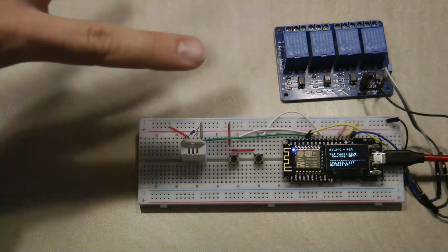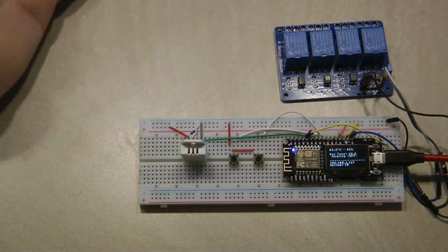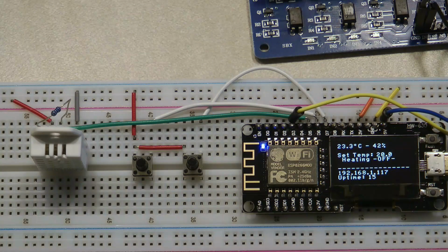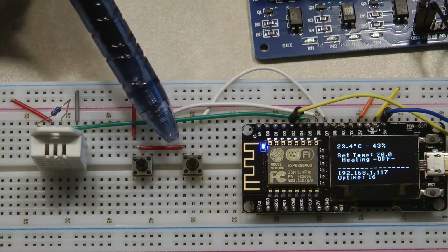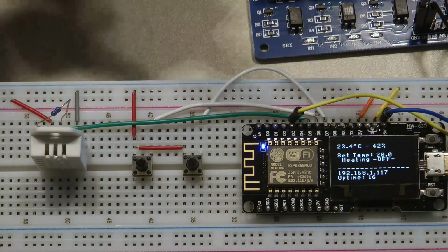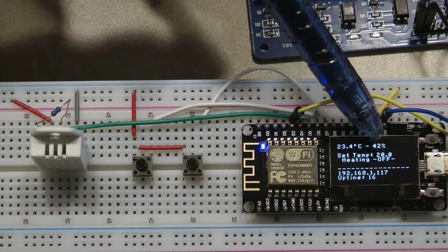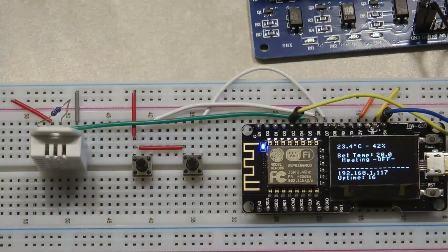And I was able to use ESP Easy with some rules and then configuration to turn it into a fully working thermostat. So you could set the set temperature on the device, and it would monitor the temperature using the temperature sensor, and it can turn the relay on and off without any additional system. So it was like a standalone unit which was working as long as the unit was receiving power. So it wasn't relying on anything else.